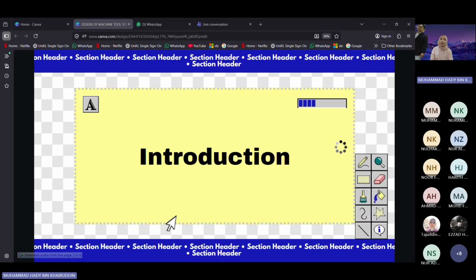Morning, everyone. When we look at a machine tool, we often focus on the spindle or the CNC controller. However, from a design perspective, the structure is the most critical element. It represents between 70 to 90% of the total machine mass. My role today is to explain why we invest so much material into the skeleton of the machine and how we categorize these components based on the mechanical function.